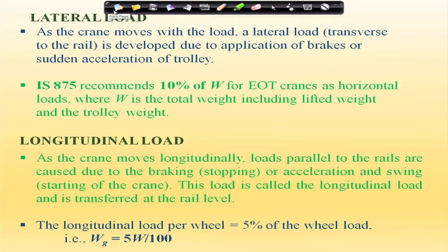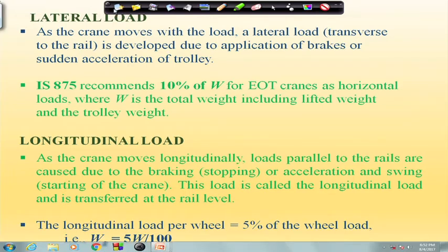So, lateral load. As the crane moves with the load, we know the lateral load will be developed due to application of brakes or sudden acceleration of trolley. So, because of application of brake or sudden acceleration of trolley, certain amount of load will be developed, which is called lateral load, right. And what is the percentage of lateral load? That is told in IS 875